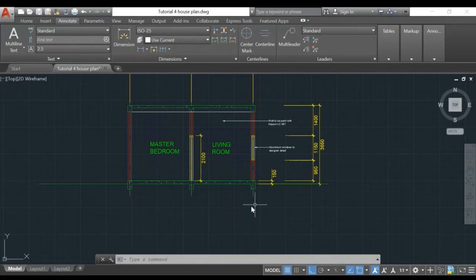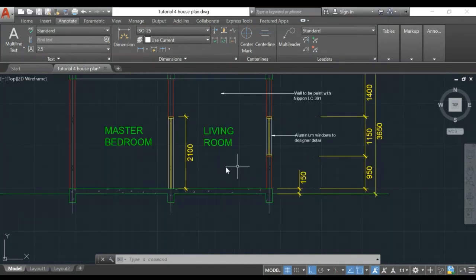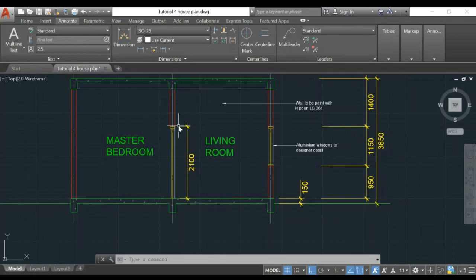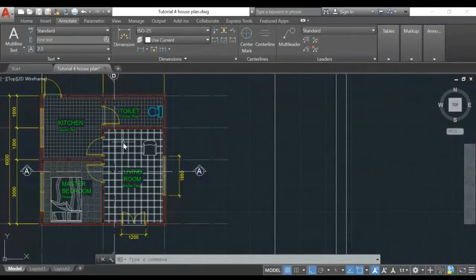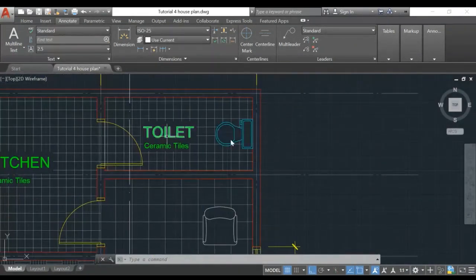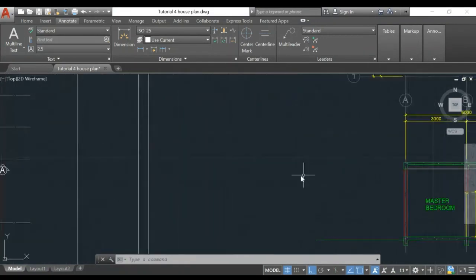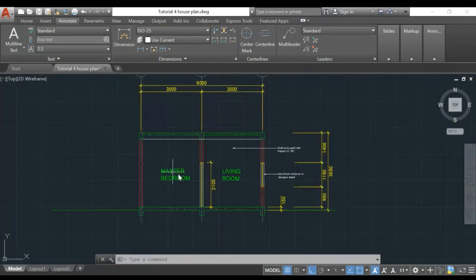So we have a dimension, we have specifications. You're supposed to draw the interior furniture. Let's say the room is, for example, a toilet. Usually a toilet has a 2000 mm height floor tile. So you should draw the hatch of tiles on the wall as well. How the wall should look, right? So you should draw that.